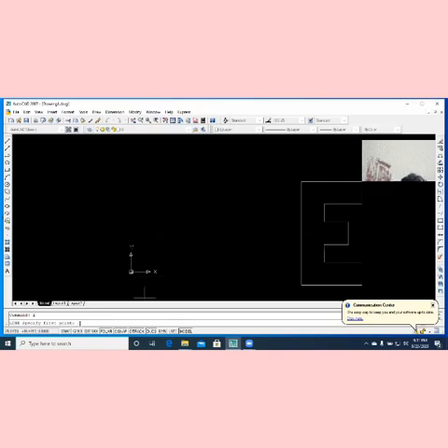So now we are using the relative rectangular coordinate method. You've taken your command, it's saying you should specify the first point. So the first point is what? 50, 50. And then you enter. So now you go to Shift at 200, 0, and then enter.